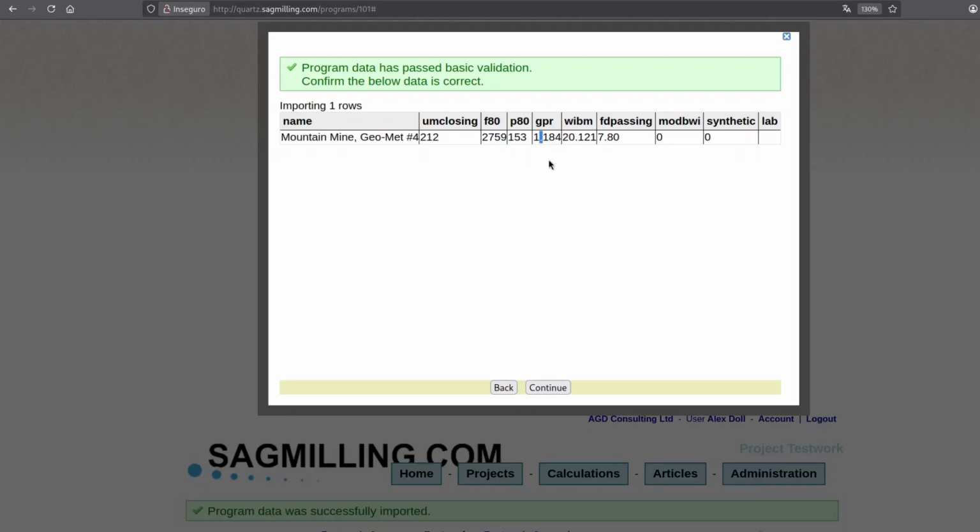One thing to watch out for is that it's very sensitive. You must have the decimal as a point and not as a comma. If you put a comma in here, or if you have a feed size that has a comma as the thousands separator, that will confuse the system. So don't include a 1,000 separator. Use a point as your decimal place.